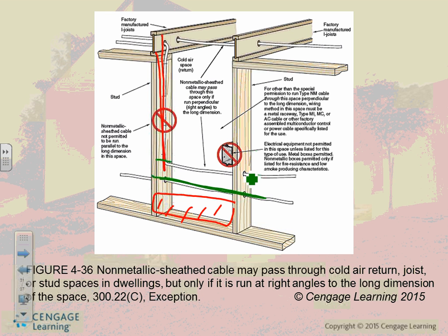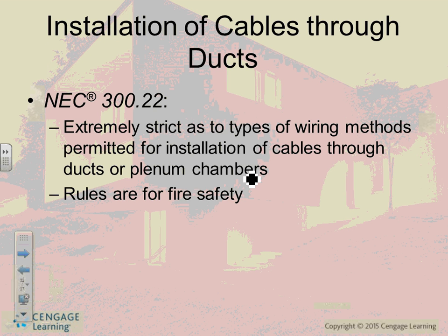But remember, this is only if you're using the cavity. If they have a duct here, like this, a duct tied to it, I don't care. Then I can bring anything I want on this wall. But if they're using the cavity as your return, and if it was a supply too, typically they don't use it as supply. You can't even do it if it's supply, and they don't do it as supply. Okay, so these are a few rules, guys, about the installation.